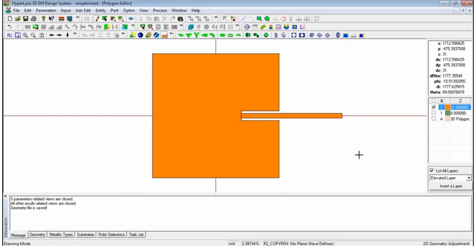The next thing is it won't act as an antenna unless and until it has been excited with our port. So we need to define a port. Port is nothing but the source from where we can excite our geometry. So we'll define a port for an edge group. If you go to port, there is an option for defining a port for edge group because this is an edge basically. You click on advanced extension is fine. You just window this edge. So port has been placed for it. So we have defined a port. So the antenna will be excited through this particular point.